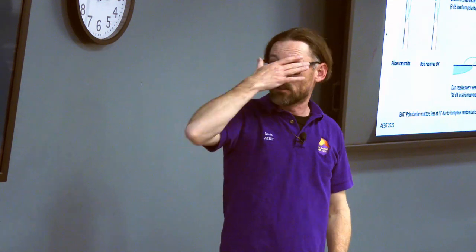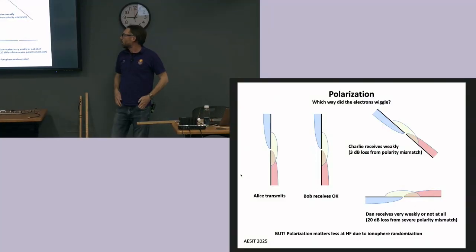So you're going to have this cross polarization. You're going to lose a lot of sensitivity, and there's transitions between. So if you're off by about 45 degrees, you lose about half your power just from being slightly cross-polarized. If you're 90 degrees off, you're completely cross-polarized, very, very little is going to get in. Not none, but very little. You're down about 20 dB from being fully cross-polarized.